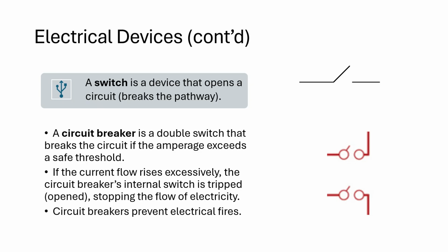Okay, and so water heaters are still wired with fuses, and the fuses will blow before current is overloaded in the water heater. Okay, the problem with fuses is once they blow, you have to go and get a replacement down at the hardware store. Whereas a circuit breaker, you can reset it. You can flip the switch back to on once you have determined everything is safe.